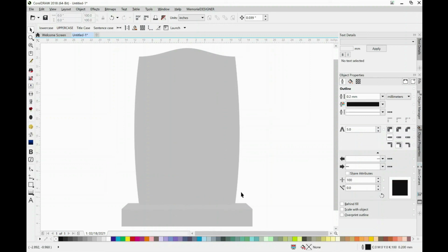So if I right-click that, you'll see the line has now disappeared. And that memorial is exactly 2 foot wide. It is 3 foot high, and it has a 2 foot drop on the OG here, and it has a 1 inch difference between the outer point on the barrel sides and the corners. Whoops, didn't mean to do that. So that's how I go about drawing memorial shapes from dimensions rather than pictures. Thanks.